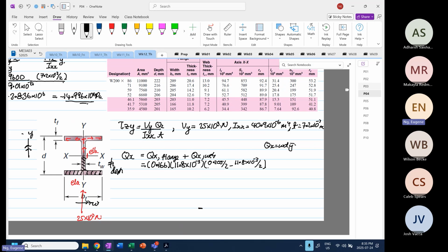Okay, this is where you have to practice, you have to have confidence, and you have to be really, really careful. Up to today, sometimes I still make mistakes. So you have to be very cautious. So the width, check again. The width is 0.166. That's your BF. The depth is 11.8, because that's the TF. So next we have to class our web now.